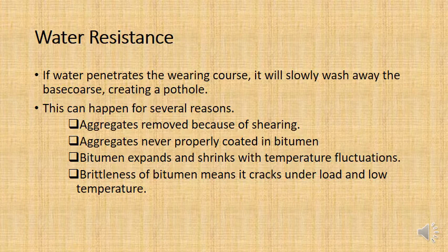It's the bitumen. And there does seem to be a tendency at times for a lot of contractors to not put enough bitumen in their asphalt mixture. The other thing is temperature fluctuations, where the bitumen can expand and shrink and become high viscosity and low viscosity.